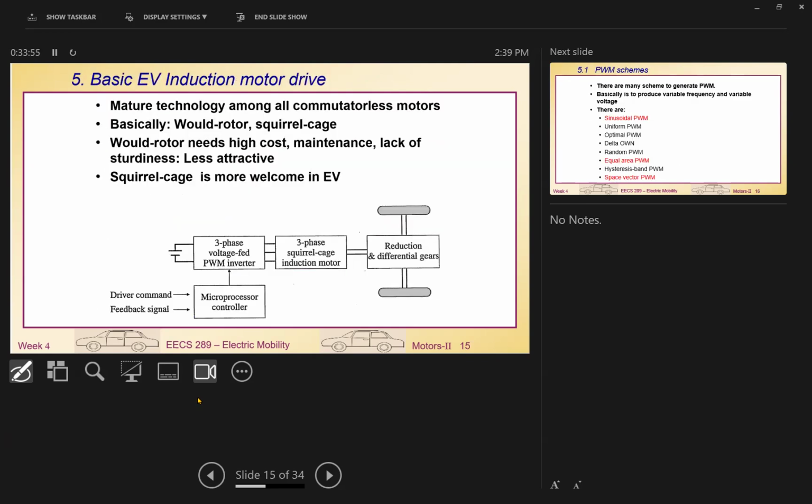So now, go back to the basic motor drive system. That's how the drive system should look. We look at the battery input for the battery system, go to the PWM inverter, and we drive an industrial motor. If it's using a single motor, then we use a differential gear to connect the shaft. Sometimes we may need to put some kind of gear in if we need to.